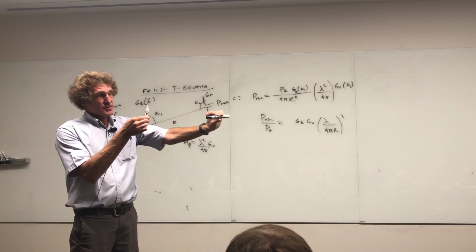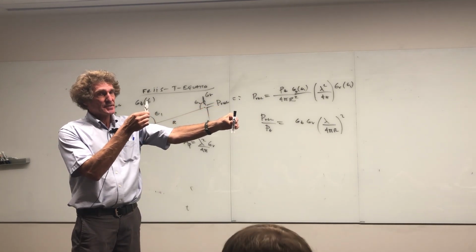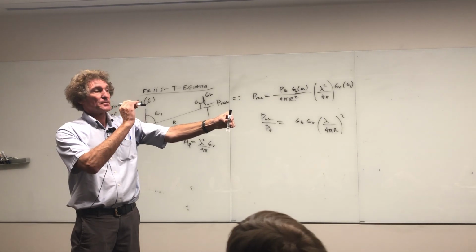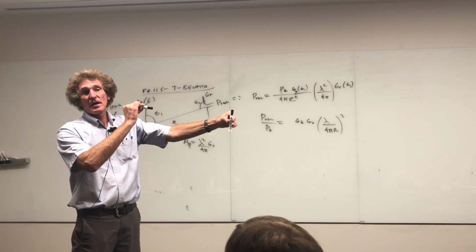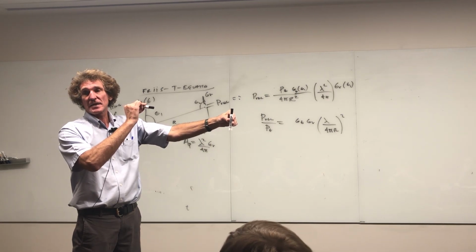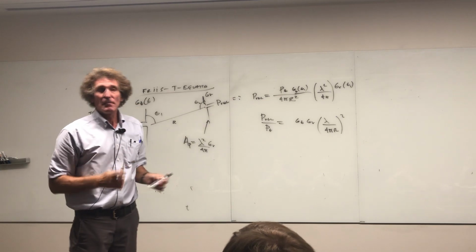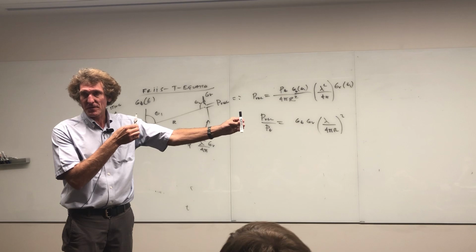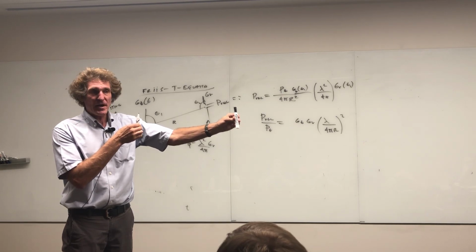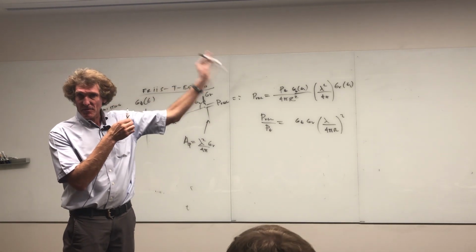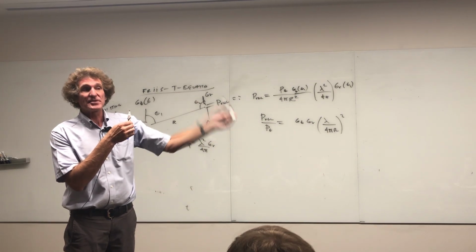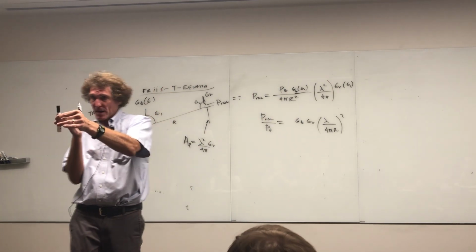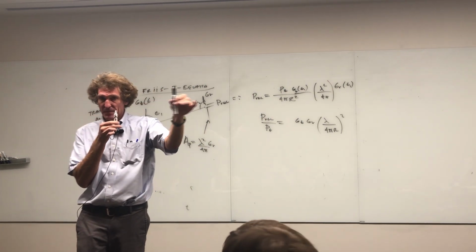All right, when it goes to this, just tell me what happens. That's max gain, right? What happens to the gain or the power received when I do this? 0, right? Because now nothing's transmitted up and down the axis of the antenna and nothing will be received. By the way, the transmitting pattern of an antenna is the same as the receiving pattern through a theorem called reciprocity. The same way it distributes power as it's radiating is the same way it receives power. So it doesn't receive any power down the ends of the antenna, and its max power received is when it's coming broadside. That's the way it is.